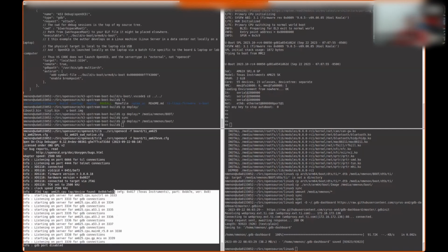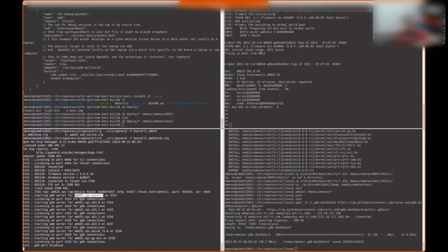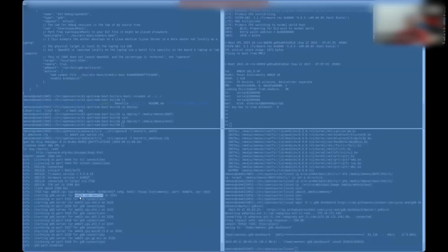There is no security control. Keep that in mind. So if you were to run your board on the internet, for example, and you were to expose this network board, there's no protection scheme in place. However, you can put an SSH tunnel in the backend. That way, the OpenOCD runs on your local ports, but the access to that is over an SSH tunnel, and your SSH key can provide you the protection. So there are different ways of skinning this, depending on how you like to do it. Anyway, back to our slides.